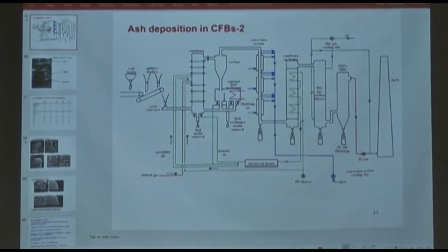What I haven't shown in here, this is a schematic. This is not a P&I diagram. The location of the thermocouples: you will have thermocouples at different levels, at different positions around its diameter. A reactor has to be properly instrumented, otherwise nothing will happen, because you cannot see what's happening. The eyes and ears of the combustor to you are its thermocouples and the pressure indicators, pressure transducers.